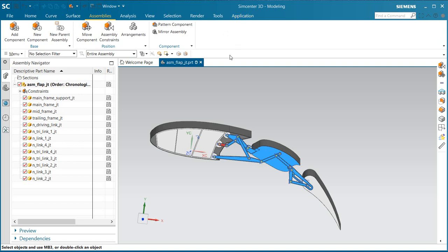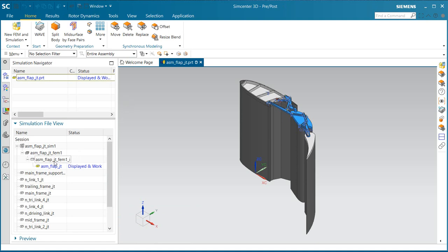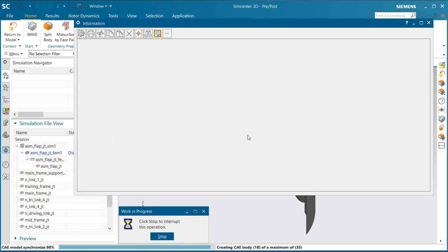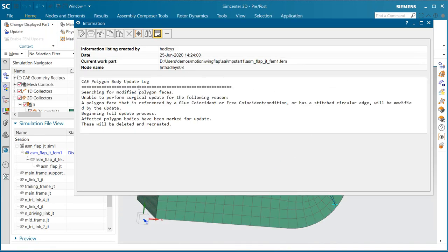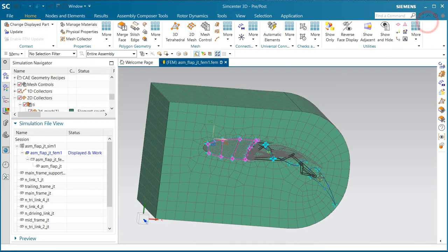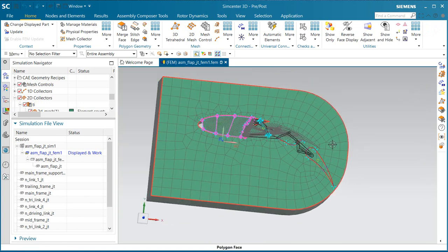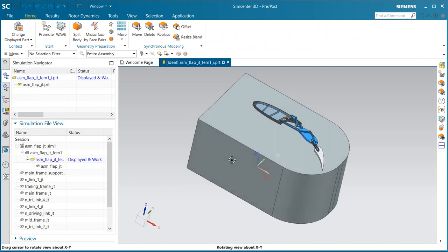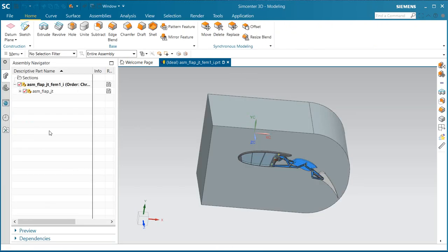Let's go ahead and update our Multiphysics model to reflect the deployed flaps. All right, so here you can see the CAD is updated. If we take a close look at that trailing airfoil, it's getting very close to the end or the edge of our air volume. Let's go ahead and tweak the air volume's location. Let's go ahead and move that a little bit aft.